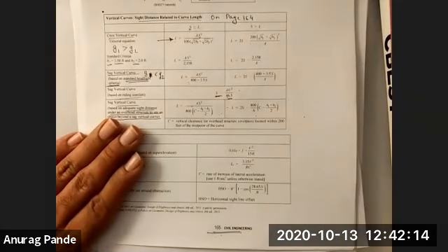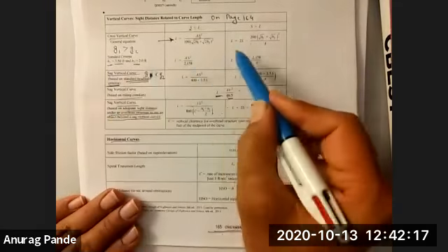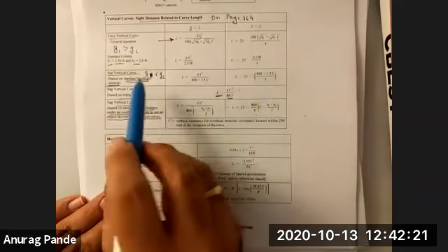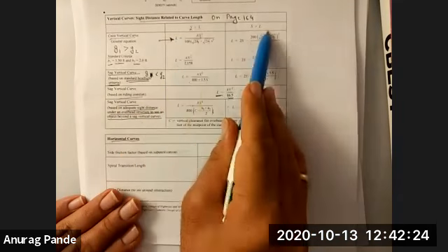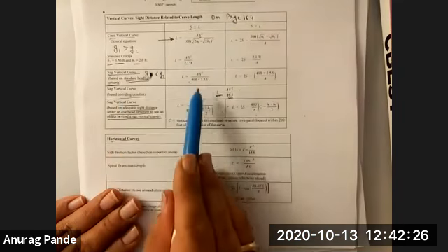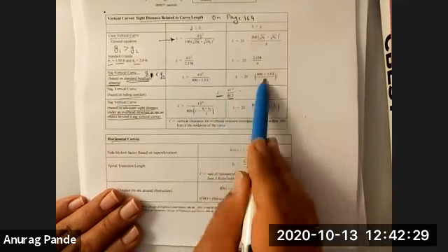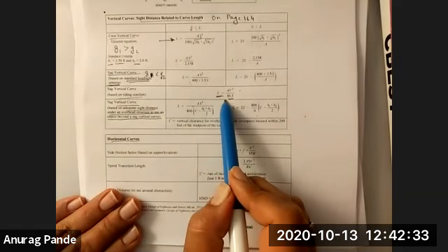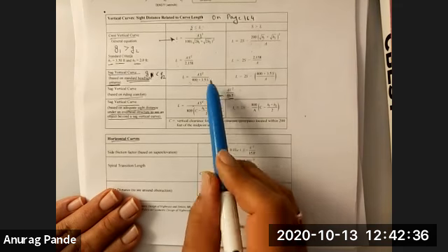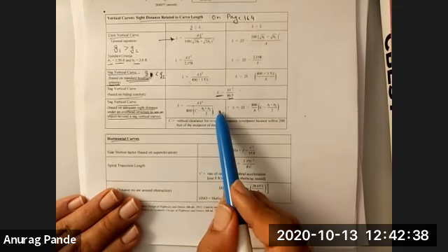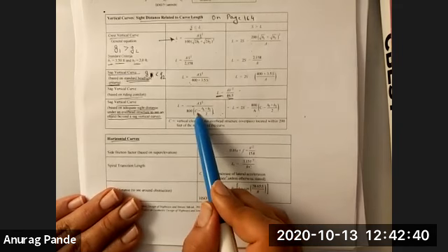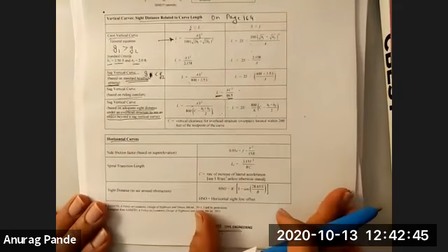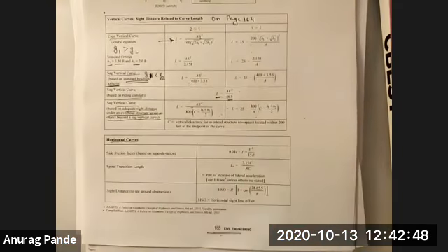And again, a lot of things to cover here. All the formula values are provided. Just make sure that the crest vertical curve has only one value to figure out. Just 2 different considerations, 2 different criteria, S less than or greater than L. But the sag vertical curve has 3 different criteria. Again, 2 different sets of formulas for those considerations, but the riding comfort is only 1 criterion. So just make sure that you understand how these formulas are provided, and all these values you can figure out. Okay, so working out some examples would be the best way.